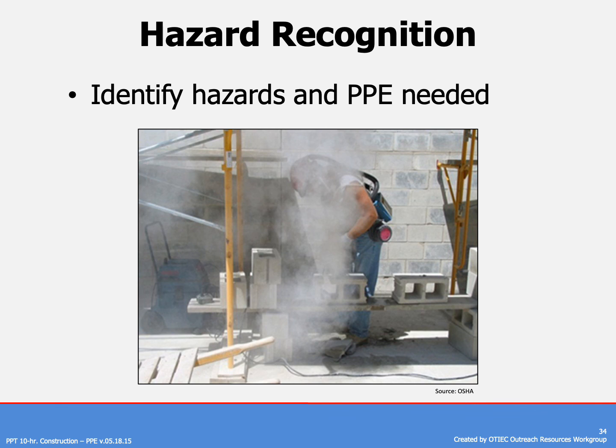Now, the one thing, it depends upon what might be flying off of there, but he's also exposed to that silica. Silica on his bare skin isn't good. It can actually become corrosive. If you have that concrete dust and he's sweating, that will become corrosive on his skin. So he really should have long sleeves on in that type of environment, in addition to proper safety footwear, I'm sure. But that's one example of doing a proper hazard recognition. You want to take a look at the whole picture, if you will, the hazard and how it can affect you from head to toe, in and out.